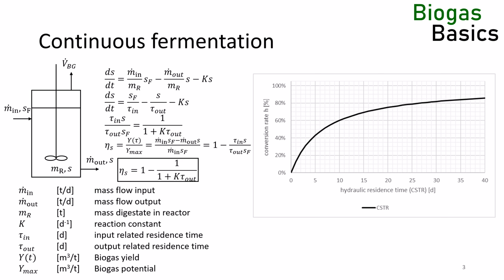as a single primary digester with a rigid roof, for example a steel or concrete roof, that is connected to the gas consumers and post-digester via one gas pipe that comprises a flow meter. The rigid fermenter roof means that the reactor cannot store biogas, and biogas that is produced will immediately leave through the pipe and can be measured.